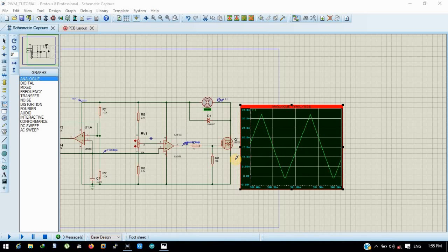Using the feature of analog analysis will give you the ability to simulate each and every part of your circuit, no matter what operating frequency you are using. This will solve a lot of problems concerning switching circuits, such as DC to DC converters or switching mode power supplies, and will give you the ability to monitor the voltage and current through the entire circuit in a real-time simulation, which will not be possible using a normal oscilloscope.